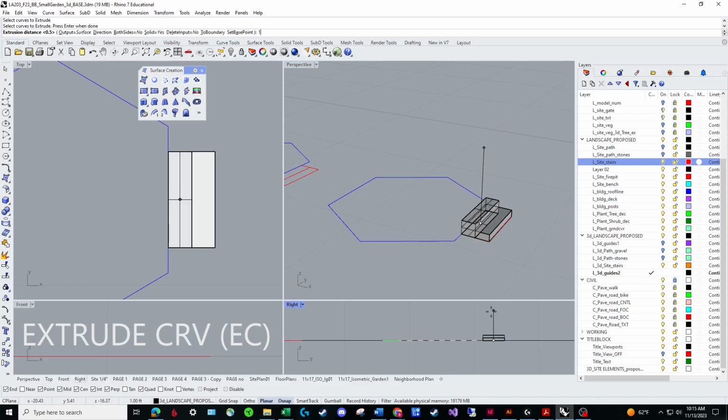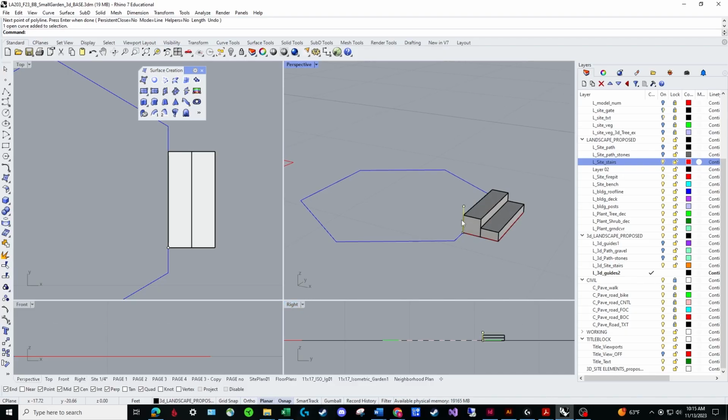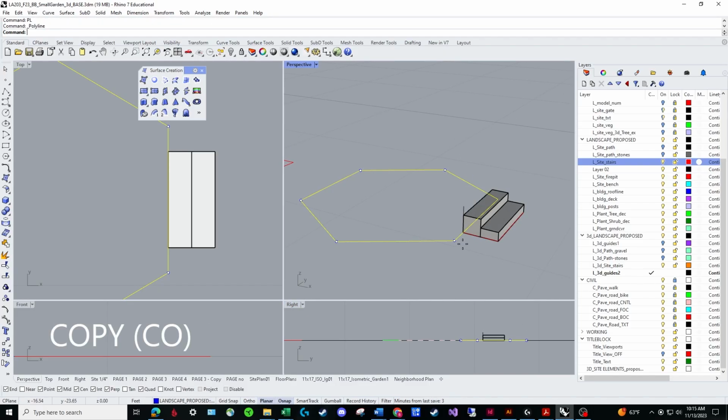And I'm just down here in the right view to make sure everything goes vertically. It should, but it's good best management practice here. And I'm going to go 1.5, and I like to hold my shift down when I do this, and then I can just go ahead and hit enter, and it'll put that at 1.5. So I'm going to go ahead and copy this up.